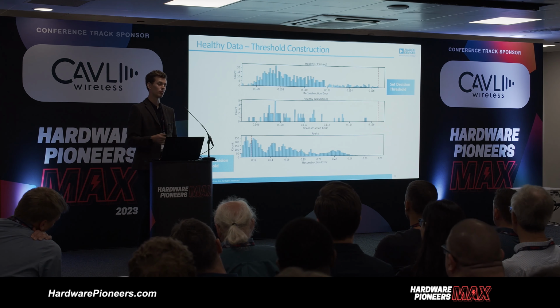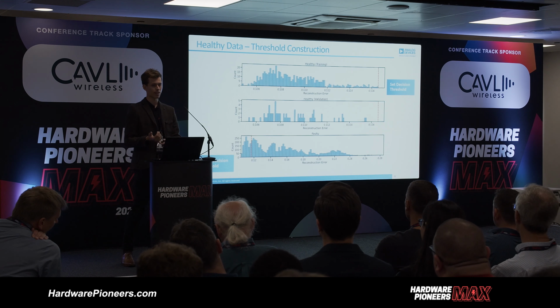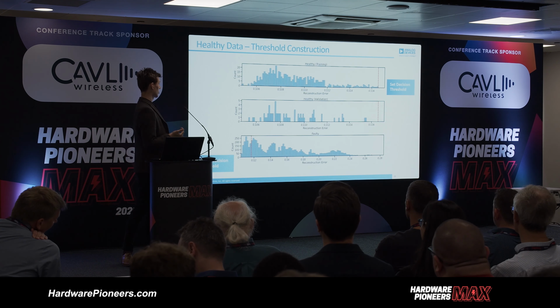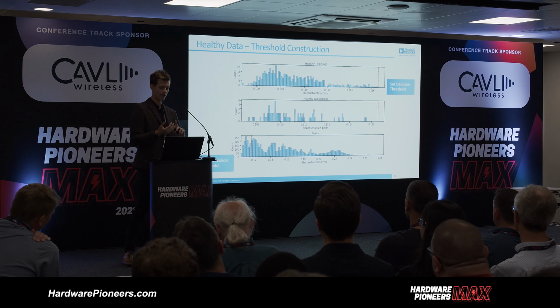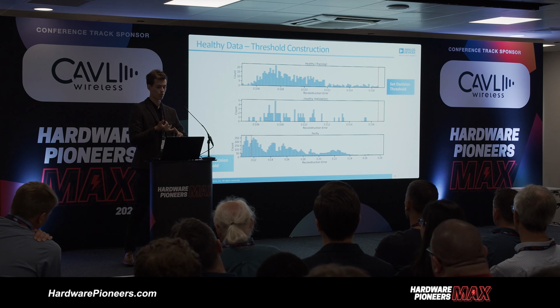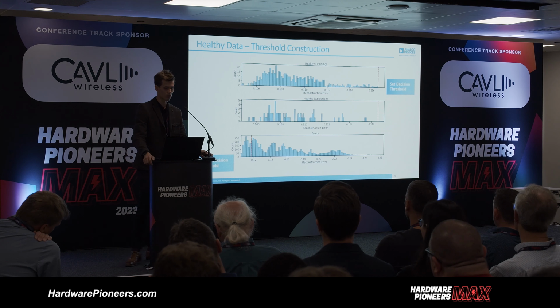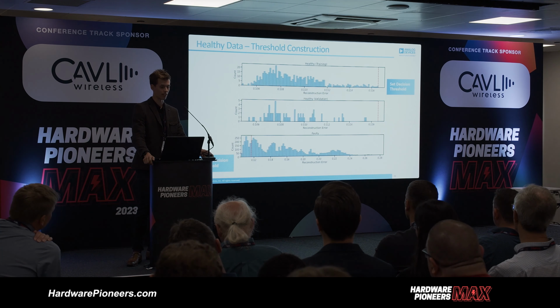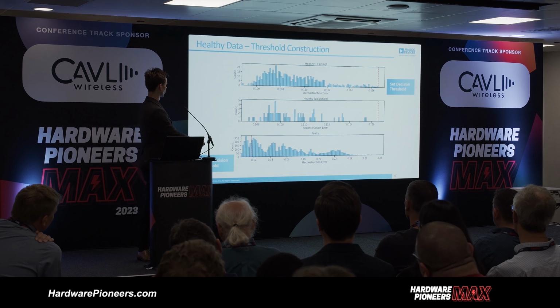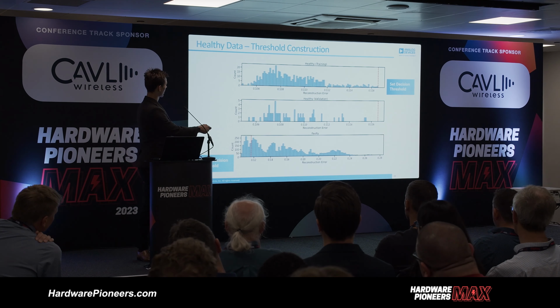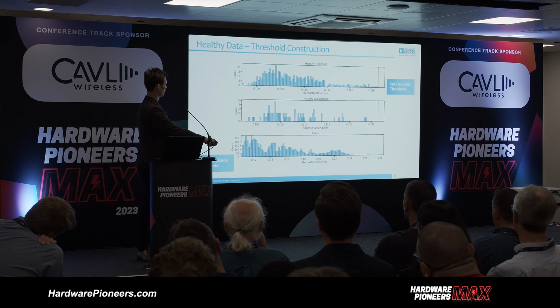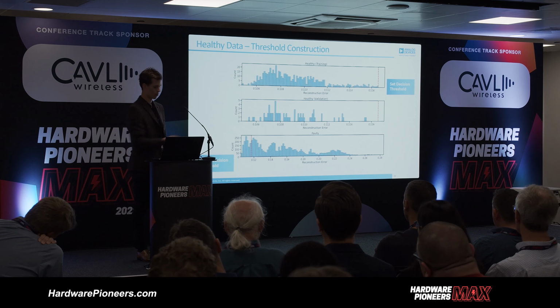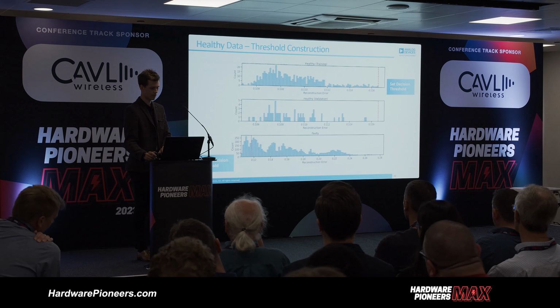So in this example, it was trained with healthy data. We have the training data at the top that is used to set the threshold of just above 0.116. We've got the validation to make sure the model has been trained correctly, and then the reconstruction error with faulty data shows the threshold set by our training data is then able to identify the anomalous data that is outputted by the tests that run on our motor.